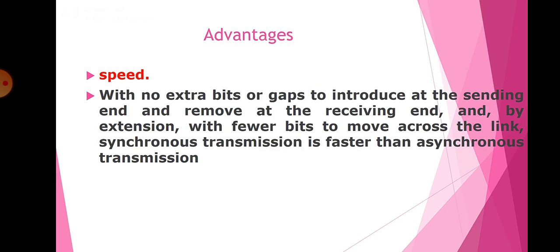Advantages: obviously speed. Since there are no extra bits like start bit and stop bit in synchronous transmission, and there is no gap between the units, the speed of the transmission will be higher, with no extra bits or gaps to introduce at the sending end and remove at the receiving end.